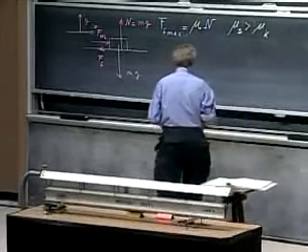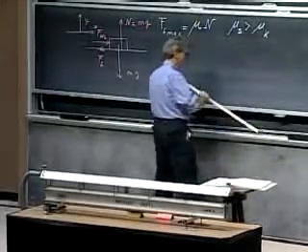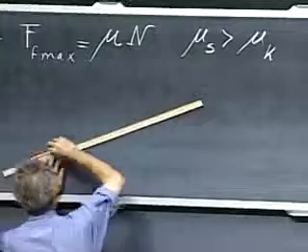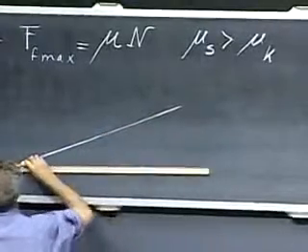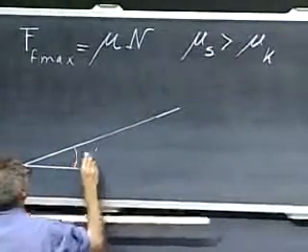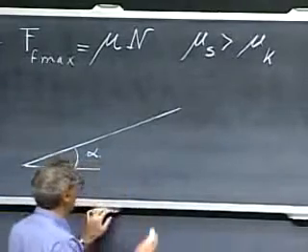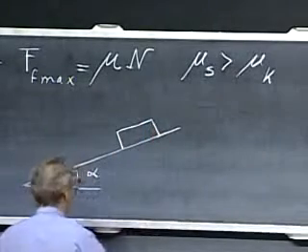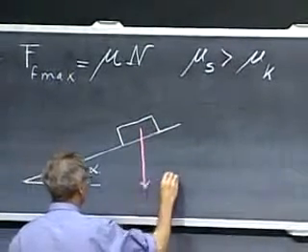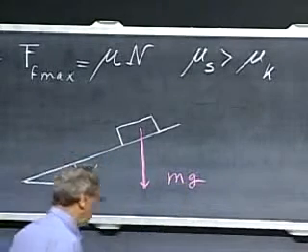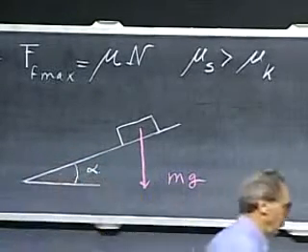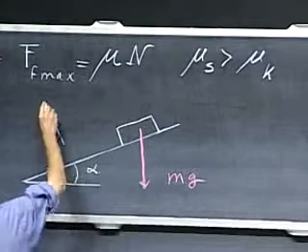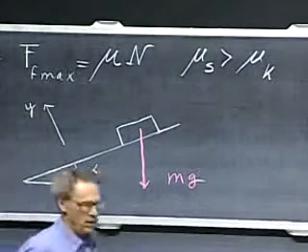It is fairly easy to measure a friction coefficient by putting an object on an incline and by changing the angle of the incline, increasing it. This is the angle alpha. You increase it to the point that the object starts to slide down. Here is the object. This is the gravitational force mg, which I will decompose in two forces. One in the y direction, which I always choose perpendicular to the surface, and another one in an x direction.